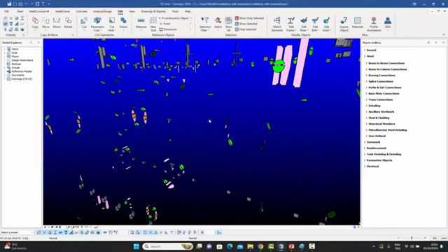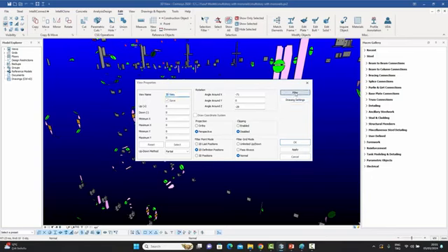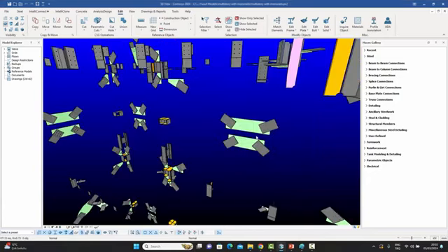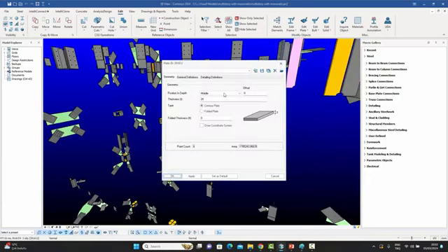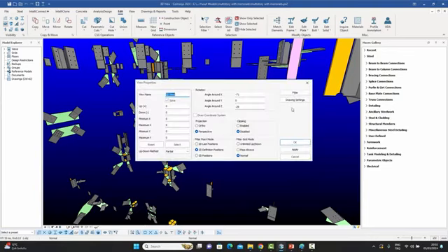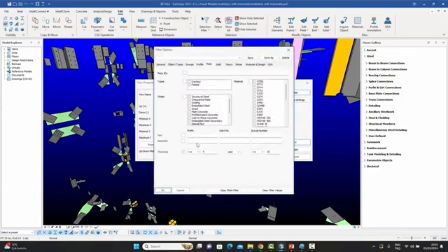But if I were to go into the filter and change it to "not between", which means show me the plates which are other than these, either less than 5 or greater than 10, and if I do that, then now I get these other plates. For example, this one is 20 millimeters, etc. So this is a very quick way of using the filter command, where previously we didn't have these options of filtering the plates in this way, and I think they're very useful for somebody who's modeling.